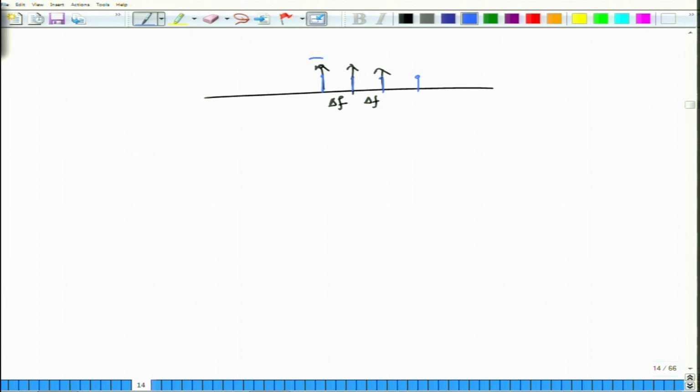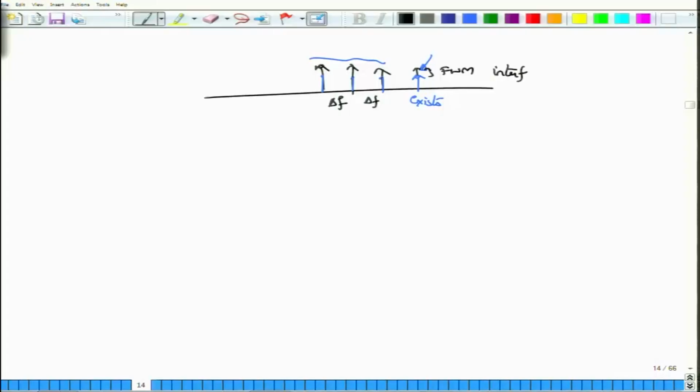So, these three can combine and fall into a new channel where a channel already exists, right, and for this channel, this extra amount of four-wave mixing that comes in is actually a noise kind of a thing, an interference from other channels. As the other channels also vary with respect to time, the amount of power that is injected into the existing channel also will change. So, this FWM is actually an interference for us.